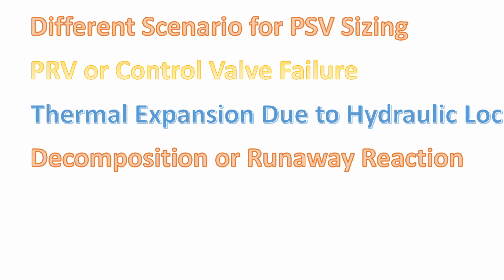Then third scenario is decomposition or runaway reaction. As we know, we call it runaway reaction for any particular reactions which display the acceleration or sudden change in rate of reactions under certain circumstances like utility failure or less agitation or charging of extra material or extra catalyst.